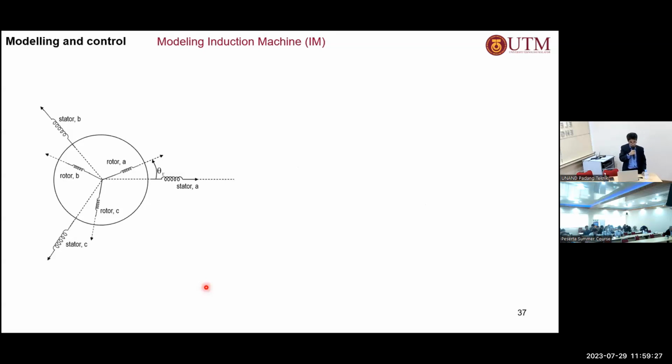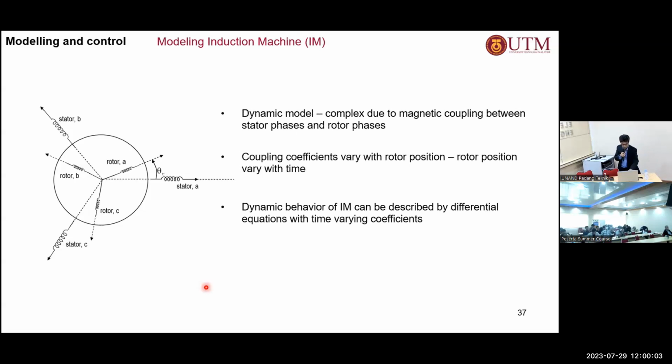This is going to be a dynamic model. We have to use a dynamic model because we want to control the transient states of the induction machines. We cannot use a per phase equivalent circuit that you have probably seen before in your undergraduate course. That per phase equivalent circuit is only valid for steady state conditions of the machines. If the voltage or the frequency varies during the transition from one frequency to another, then the per phase equivalent circuit, which is a steady state model, is not valid. That can only be described using the dynamic model of the induction machines.